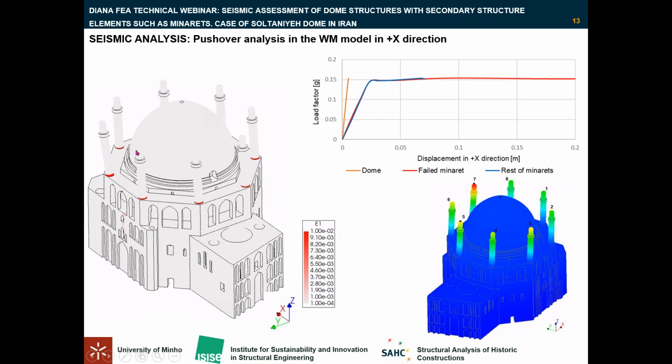As you can see in this picture, the damage is more pronounced at the base of the minarets, characterized by diagonal and horizontal cracks, while minor damages appear on the main arches in these parts, in the first and second floors. The masonry walls of the dome hall present no damage. Furthermore, no damage is identified on the dome nor in the tomb area. Here and here and in the walls we can see no damages.